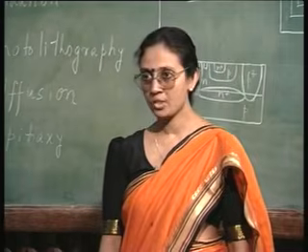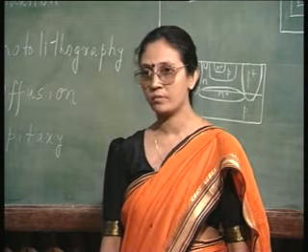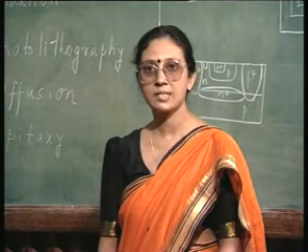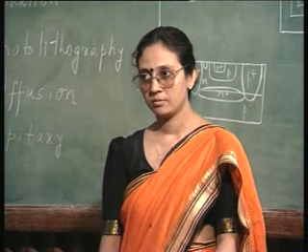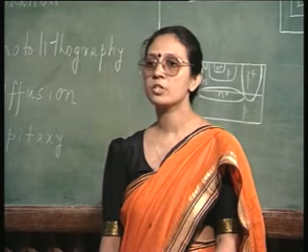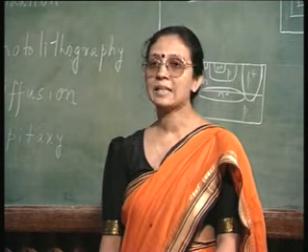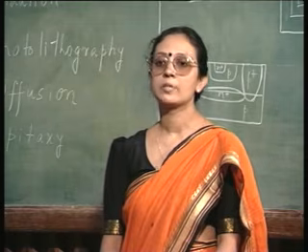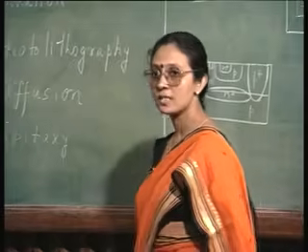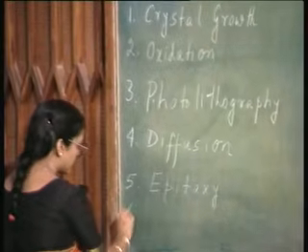Okay. So, your transistor is almost ready. You have the emitter, you have the base, you have the collector, you have the isolation between adjacent devices as well. What is remaining? To establish contact with the outside world, right? And that is done by a technique called contact metallization. So, that brings us to process step number 6.